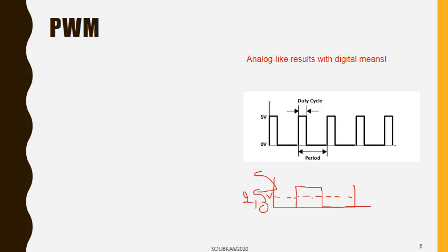And bingo, this is exactly what we need to control the different speeds of a motor. All you have to do is control the uptime and then get the mean, in order to have a particular voltage that can vary between 0, no rotation at all, and whatever the full voltage is, for the highest speed. Fair enough? The uptime is called the duty cycle, and this is usually a percentage.